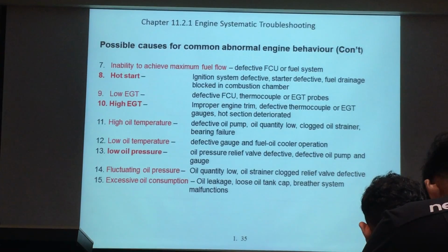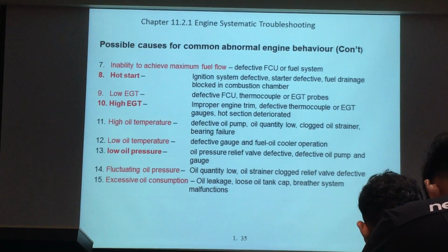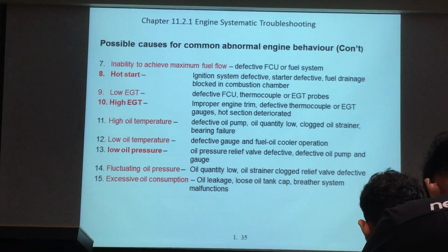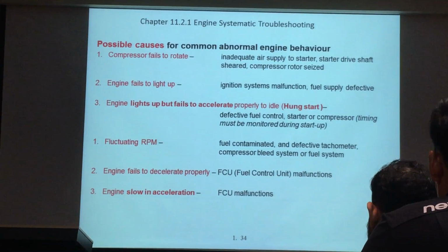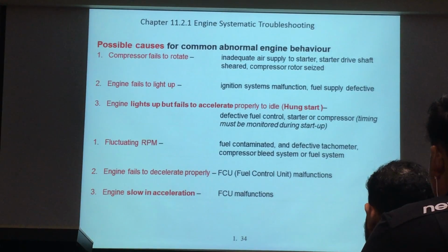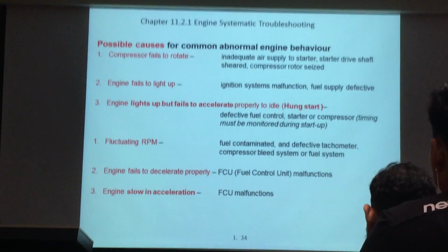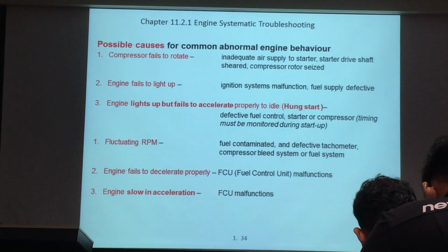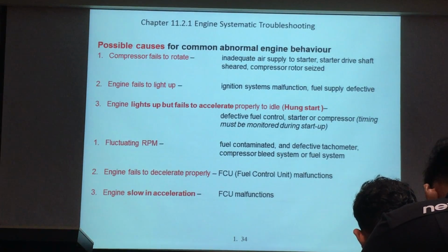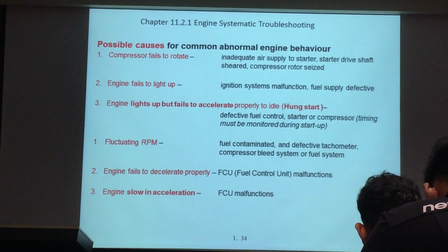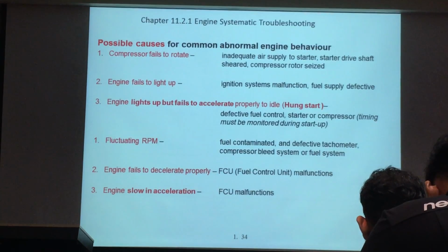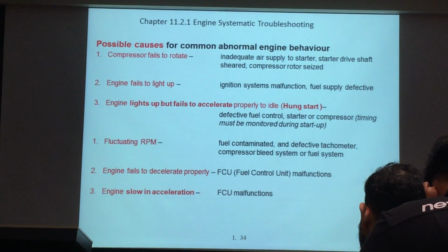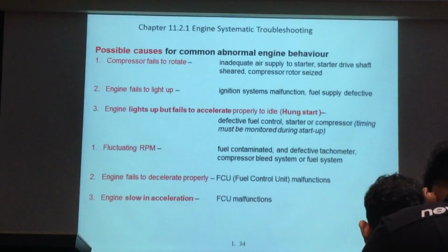Now what about the hung start? Number 3, FCU failure. A hung start means your engine cannot achieve idle RPM within a certain time; it hangs. Who to blame? FCU. The next one is your starter: too weak, cannot accelerate. Or the compressor is too heavy; remember your start bleed valve must open properly, otherwise the compressor becomes too heavy to crank, and you get a hung start.